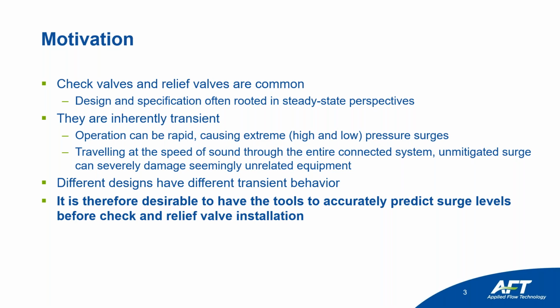So you want a check valve or a relief valve generally to act quickly. And if it acts quickly at the wrong time, that can cause some pretty extreme pressure surge, both high and low. And that pressure surge, just for background for people that need the additional primer here, is going to travel at the speed of sound through the entire connected system.